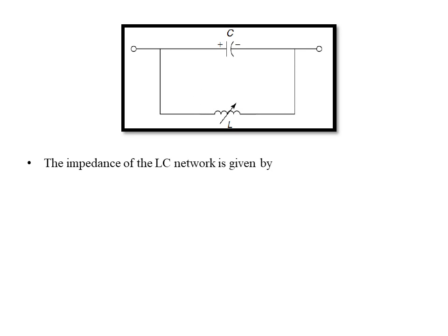So in figure 1, we have shown a capacitor connected in series and back-to-back thyristors connected in parallel with the series capacitor, that means it is simply an LC branch or LC network. The simplified diagram of figure 1 is shown in figure 2. From this figure, the impedance of the LC network is given by, now we have two impedances over here, capacitive impedance and inductive impedance. So we need to calculate the equivalent impedance of this circuit. Z equivalent is equal to XC, the reactance of the capacitor, into XL, the reactance of the inductor or back-to-back connected thyristors, divided by XC plus XL.